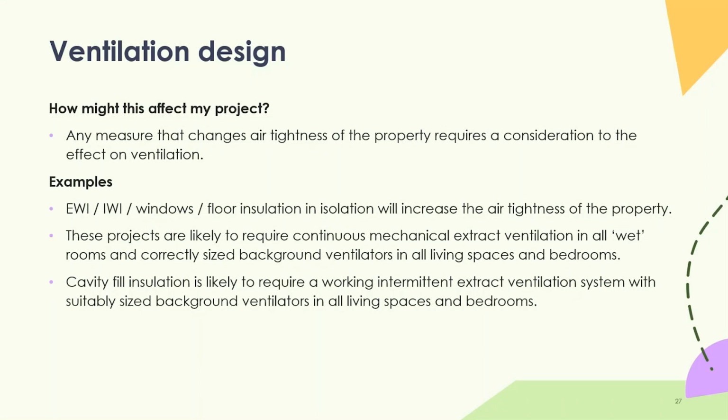Again, the temptation is for people to think, oh, I don't want to lose all my warm air, and they can be tempted to switch off ventilation, but it makes such a big difference in terms of keeping damp and mold to a minimum, having that background ventilation going. And the improvements with the insulation, draft proofing, better windows, better doors, etc., will far outweigh any heat losses through improved ventilation.